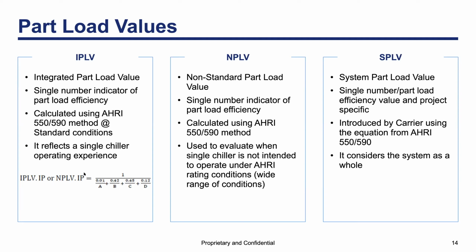And this is important because when retrofits or optimizations are being considered, we need to model the system before and after, so we provide a better and more comprehensive analysis of the energy consumption of the system and not just the chillers. And then, of course, we can translate all these numbers, this overall energy indicator, into financial terms, whether it is payback, net present value, ROI, return on investment, or whatever we need.